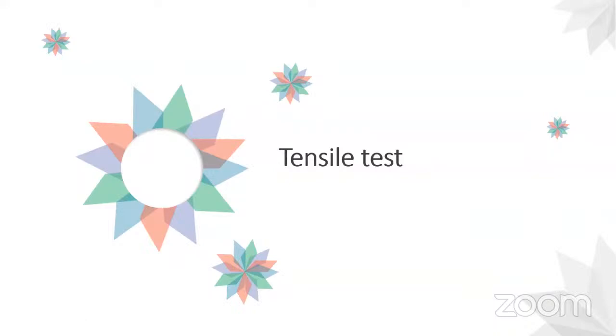Since yesterday we have started the part related to the testing of polymers or polymeric materials, or you can say plastics. In yesterday's lecture we saw that the major part of testing polymers is the identification of polymeric material through different processes or different types of testing. It starts from basics like the flotation method, to the hot rod penetration method, to incineration.